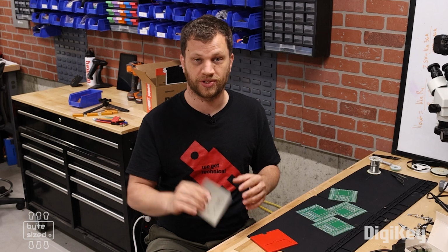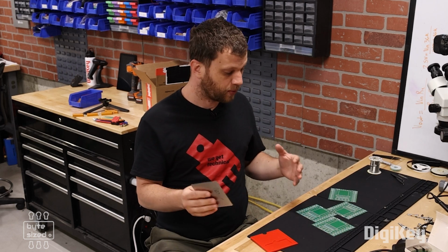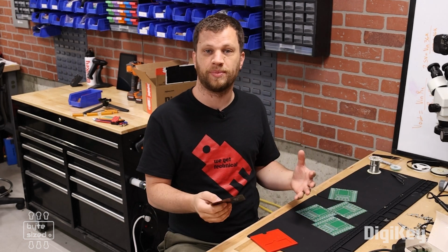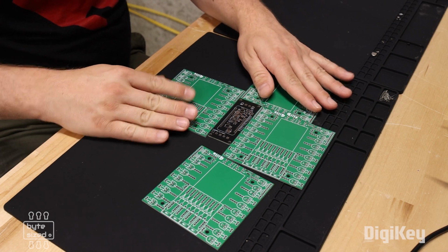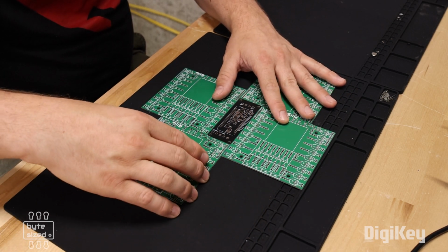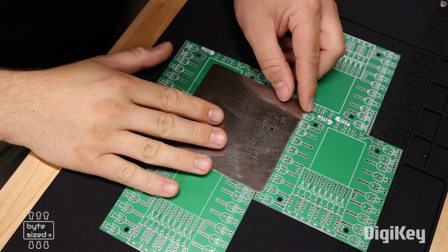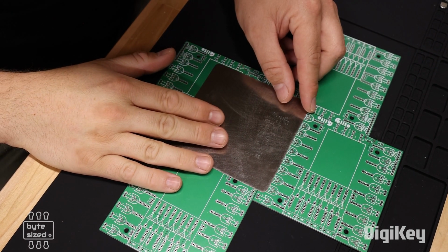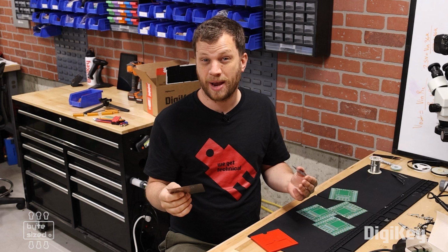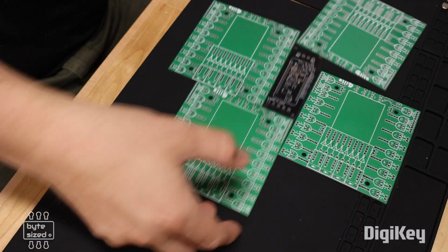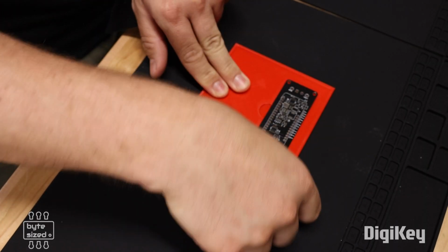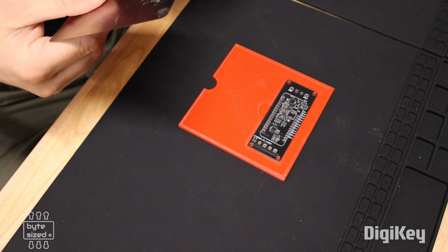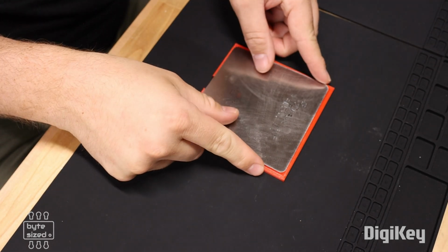And to do that, I'm going to use the stencil that I ordered, and normally what I would do is I'd get some old PCBs and I would line them up and give myself sort of a frame or a little jig to put my PCB in, and then I would have to manually align the solder stencil with the pads on the PCB. But this time I decided to try something new. I designed and 3D printed a little jig that I can stick the PCB in, and then it automatically aligns the stencil right where it needs to go.